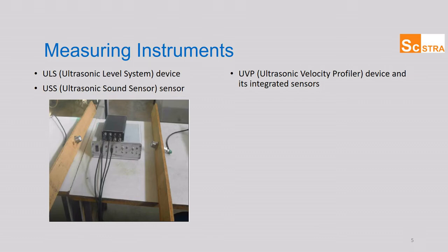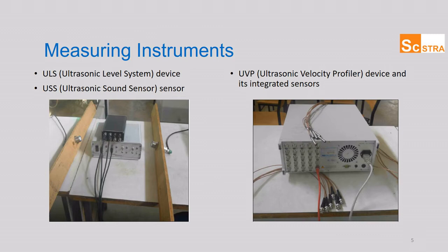We use these sensors to measure time-dependent water levels. We use these water levels to obtain wave height and wave period accordingly. Then the ultrasonic velocity profilers are used in the studies to measure time-dependent scour or deposition depth.